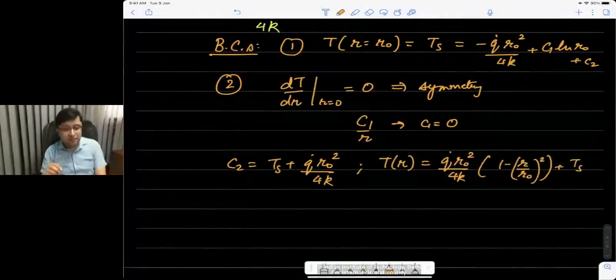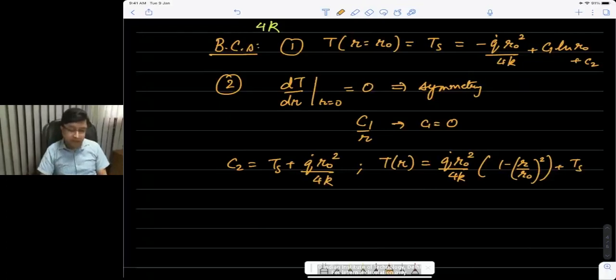And that is actually the same. I'm surprised that none of you recall that, but when you did fluid mechanics, this is the same as a pressure driven flow example. There the dependent variable was velocity. You had a flow in a pipe where u was a function of r only, and so you get a parabolic profile, and that is what we have obtained. There's nothing different. And you did the same thing there again. If you recall, at the center at r equal to 0, you would have said that the solution has to be physically bounded, so you take c1 to be 0.